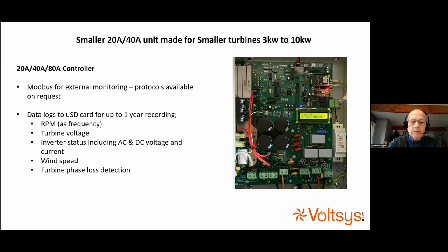That's particularly important if you have a turbine where you're using a frequency-based power curve. If you have a voltage-based power curve and you lose a phase, the voltage will fall and the generator will generally stop, and the inverter will generally stop pulling power because the voltage will have fallen off the power curve. But the frequency might remain the same, depending which phase you lost. If you lost the phase that you're measuring, the frequency will fall off and the inverter will stop pulling power.